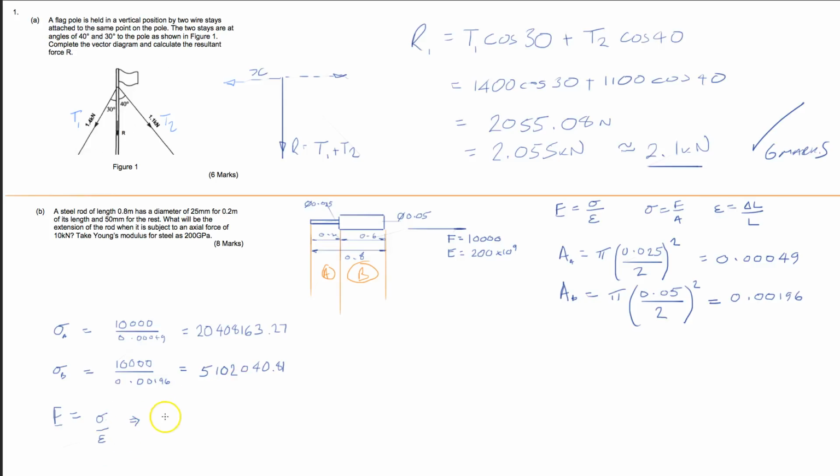So I can rearrange this to be strain is equal to stress divided by big E. Yep, checks out. So then I can go and plug this in here.